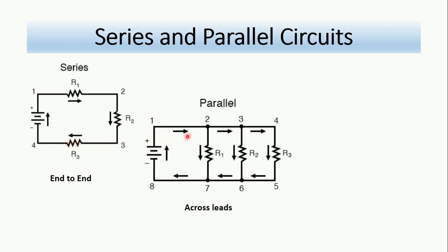if you look here in this parallel circuit, for example, if we assume that the values of the resistors are equal, so R1 is equal to R2 is equal to R3 is equal to R, then this implies that the total current flowing here will be divided equally among all these three resistors. So the current flow in R1 will be equal to the current flow in R2, equal to the current flow in R3, and still they are in a parallel connection. So saying that the current flow in all resistors must be the same in order to be series is a necessary condition, but not sufficient.